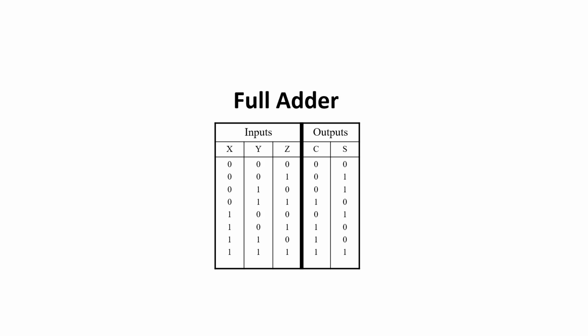So actually the decoder can be used to build any function. This will be in the exams or quiz or whatever. I will ask you to do it on standard gates. I may ask you to do it by NAND gates, by NOR gates, but at the same time, I will ask you to build the system by using a standard decoder, and this is what I'm going to show you in the next slide.